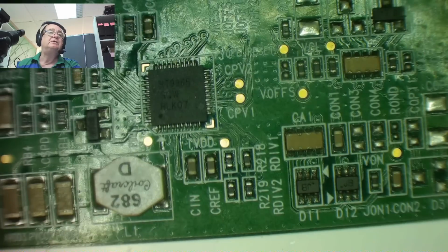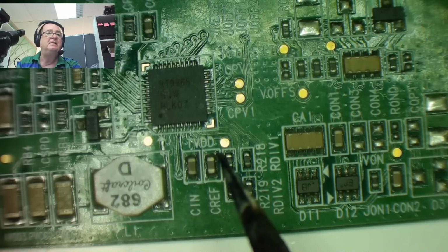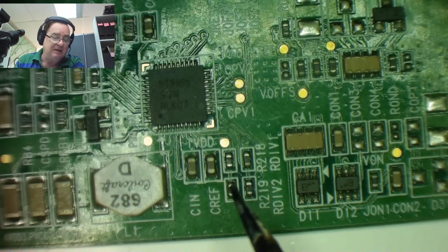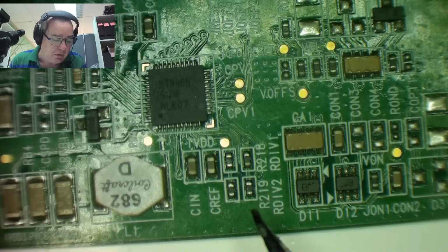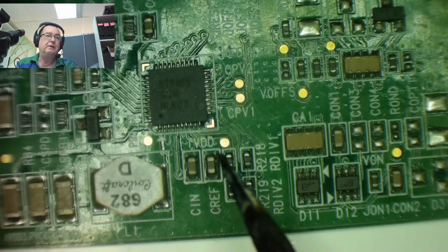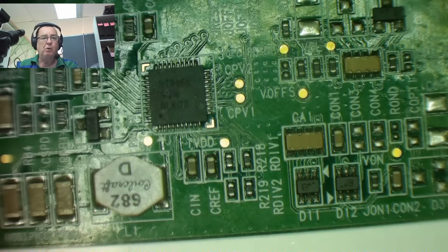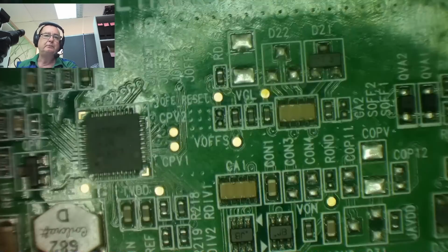There's another one that says TVDD, and we were looking for a DVDD. But again, this is a test point that we've looked at before when I first went across the whole board, and I made the note of the voltage on this one, 2.54. So again, whatever it is, the same. In fact, we know all these test points are the same.